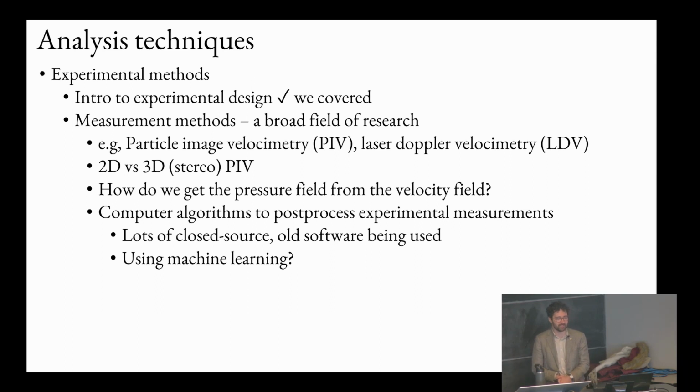PIV is called particle image velocimetry. I think I mentioned this before. Basically, you seed your fluid with a bunch of particles and shine laser beams through it, and you can track those particles and use that to measure the velocity field. That's a state-of-the-art technology, especially because there are some labs in the world that can do laser sheets from different angles and do a stereo version of this. Normally PIV is limited to 2D, but you can get 3D versions. There are only, I think, one or two labs in the world that can do stereo PIV.